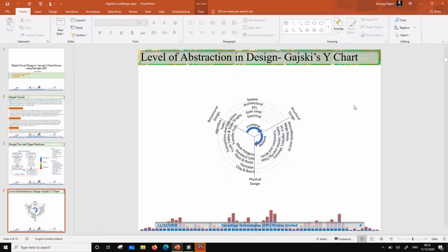So these different components are connected to make what is called standard cells, and these standard cells are well tested and optimized over a period of time, and then you have a library of these standard cells. So let's say I have described a circuit as a HDL or hardware description language, and then I would have an algorithm to map this HDL to standard cells. So that way I can directly target an ASIC instead of FPGA coming as an intermediate step, right? So this form of development would be called design using standard cells. This is what we are going to do in this series.